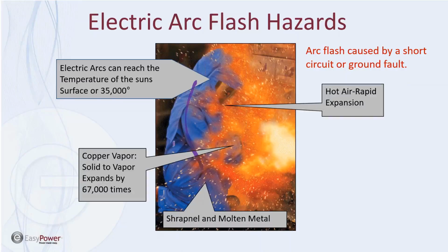However, one thing to think about is you still have molten metal, and if your risk assessment says that the molten metal is outside the arc flash boundary, so I don't need a shield. Well, you may want to consider a shield anyways, because even though it's not going to burn your face off, there's still molten metal, and it could cause pits in your face and so forth. So you might want to try to avoid that.